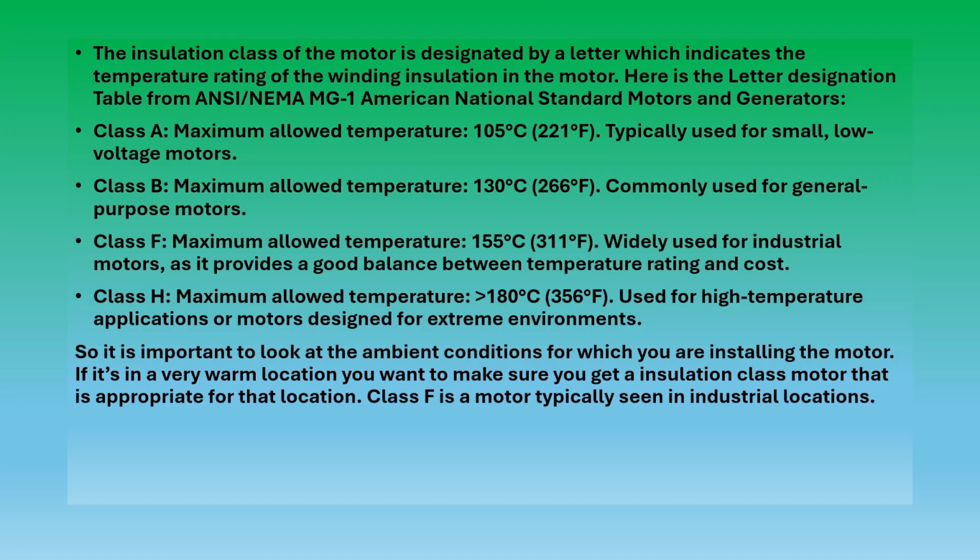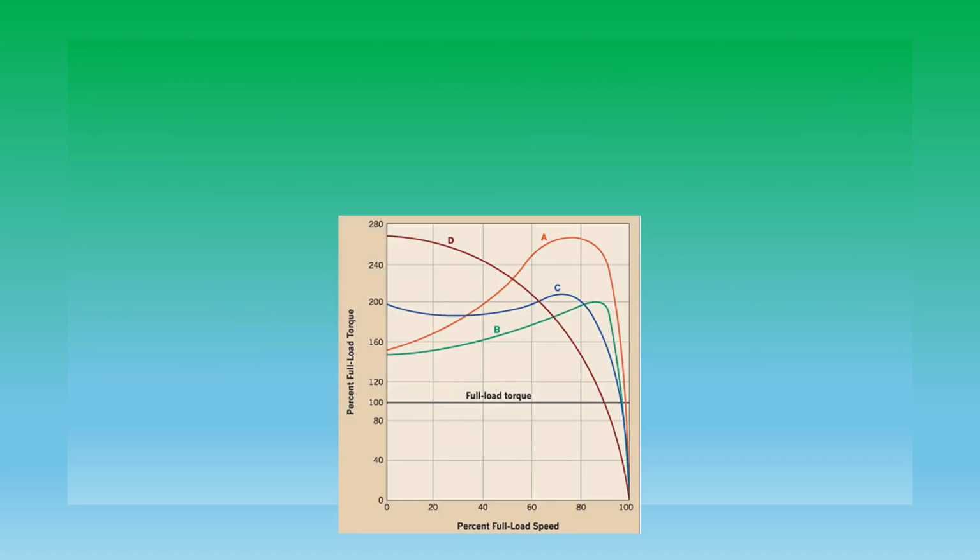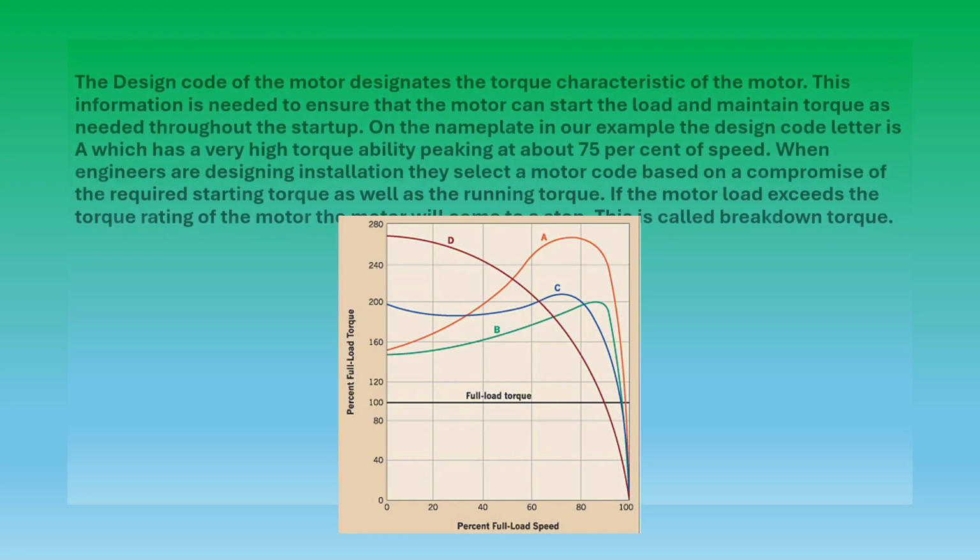Class F is a motor typically seen in industrial applications. It's the one I've seen most of. I have seen some Class H where we've had some peculiar circumstances that required a high temperature withstand.